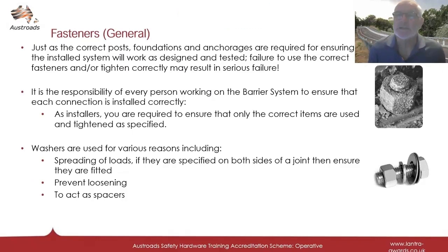Now we'll look at fasteners. Just as the correct posts, foundation and anchorage are required for ensuring the installed system will work as designed and tested, failure to use the correct fasteners and/or tighten them correctly may result in serious failure. It is the responsibility of every person working on the barrier system to ensure that each connection is installed correctly.